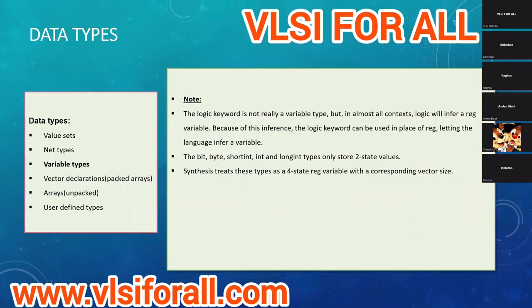Simulation is basically where you run your design, the RTL. RTL is basically when you code your design in one of the hardware description languages. When you run that, then this probably will be taken as 2-state variables. But when you synthesize it, so when you create a netlist, I hope you guys know what a netlist is, but for those who don't know, when you write your design in a hardware description language, VHDL or Verilog, now to do static timing analysis or layout or placement, whatever comes towards the next step of the VLSI design flow.